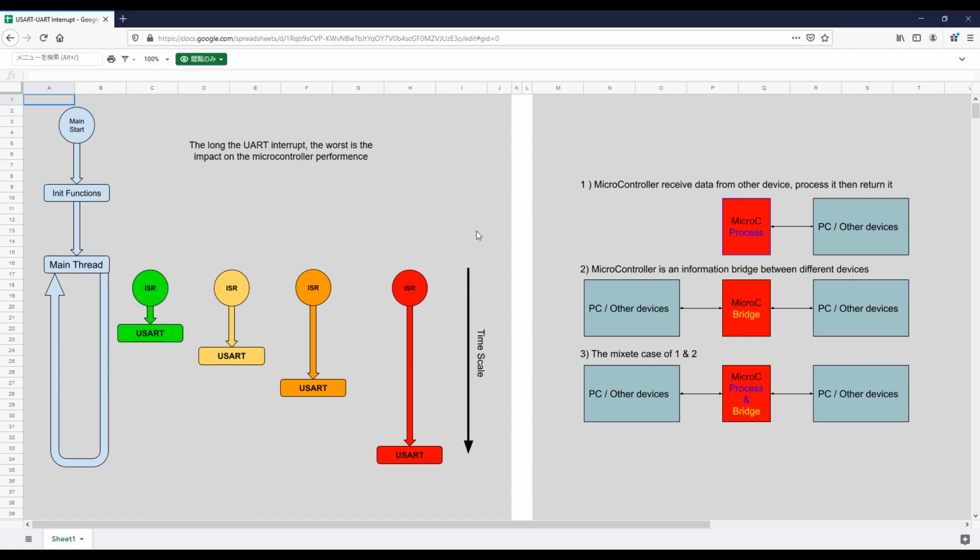which are happening. One of the rules that is really common and must be respected is to have your ISR as short as possible, which means that you should not use a loop, a while or a for, inside your ISR.